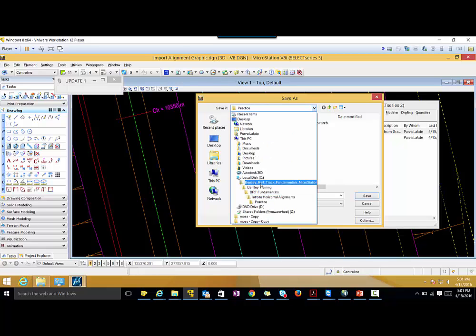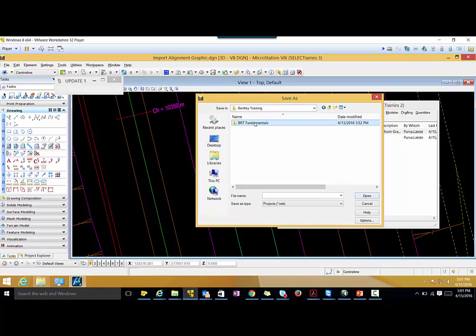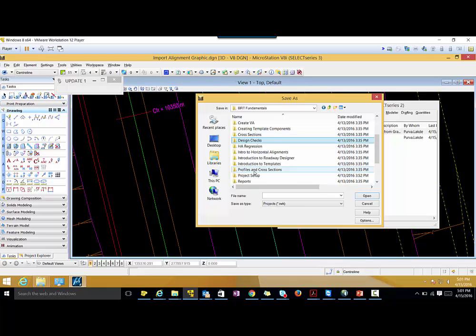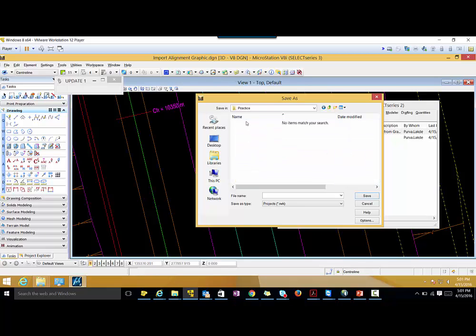Now I will browse to Bentley Training, BRT Fundamentals, Introduction to Horizontal Alignment, Practice, and I will type import from graphics, and I will save this file.